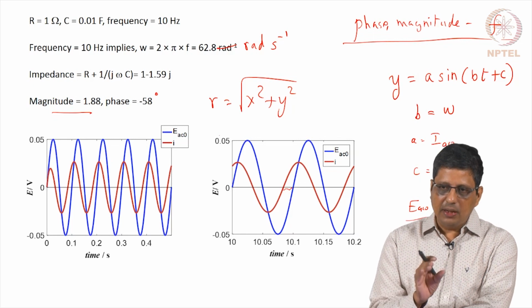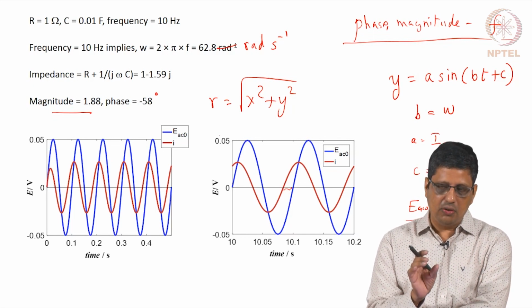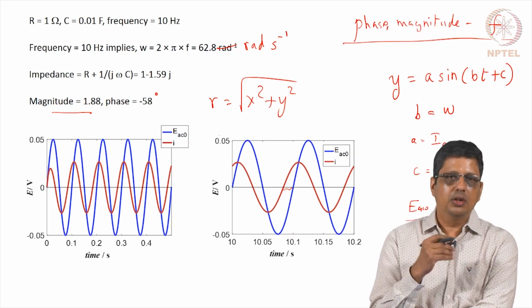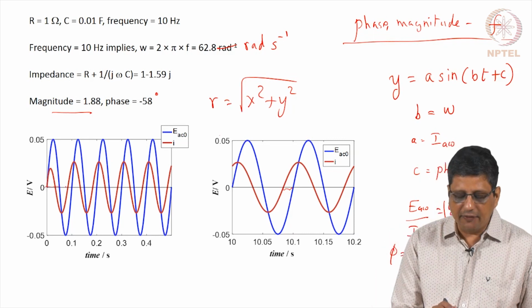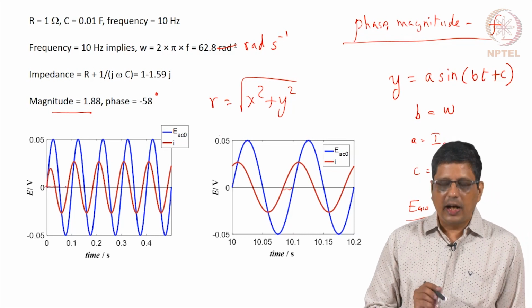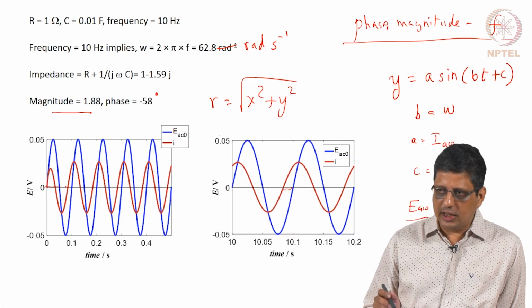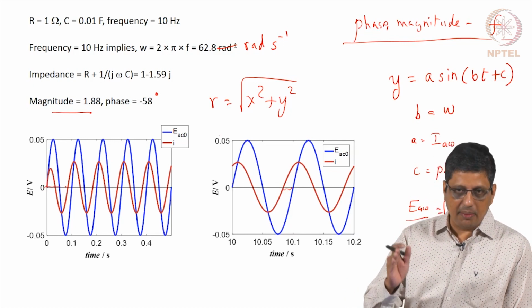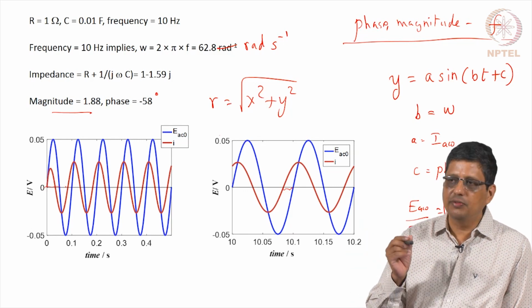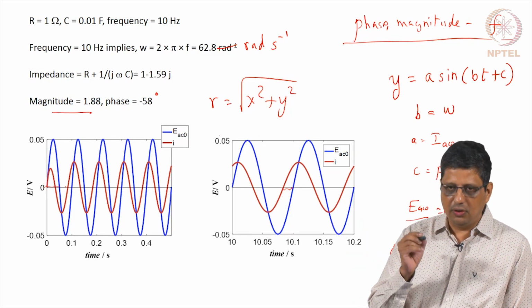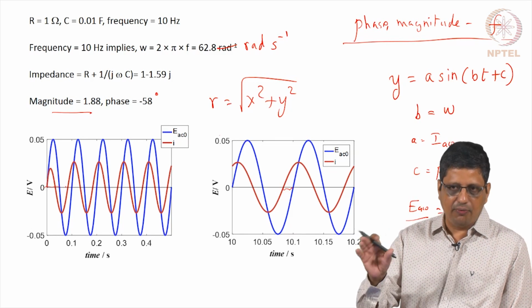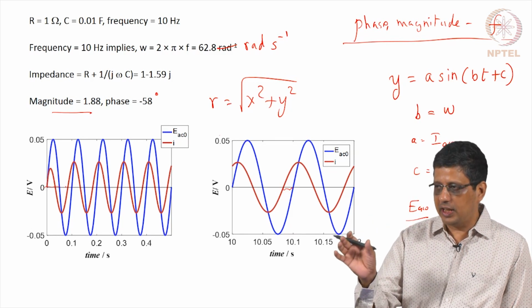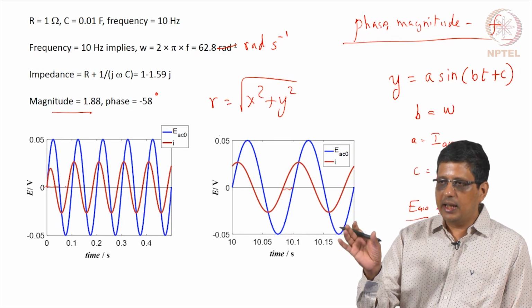So, sometimes you will have to use the ODE to solve to understand certain things. You also get to know one more point. If I take the first cycle and fit it to this equation or do the Fourier transform, I will not get the correct values. I have to wait for some time and take the steady periodic results. That means, when you do experiments, you will have to apply the cycle, wait for some time for the system to stabilize, or for the response to stabilize, and then take data.